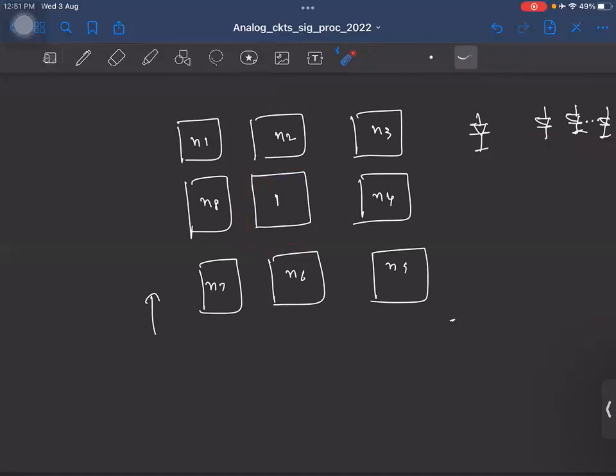And this will be a very recurring theme in circuit design, because you'll often find you can't have two quantities matched exactly. So the next best thing you can do is try to match them on an average. You'll see this in many kinds of circuits later also. And this is what is done in practice. Now it might make sense why you want to choose N to be 8, because totally you will have 9 diodes. So you can place them properly in this kind of a symmetric fashion.